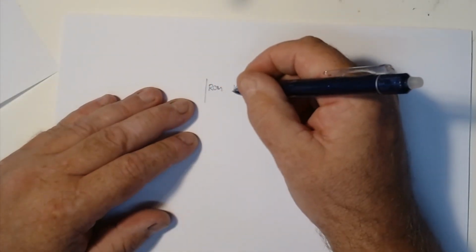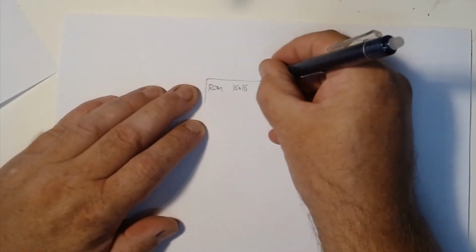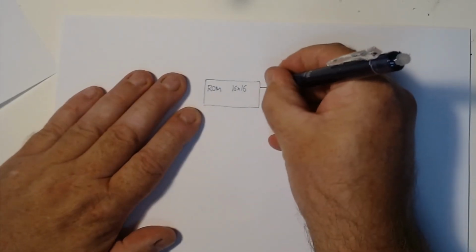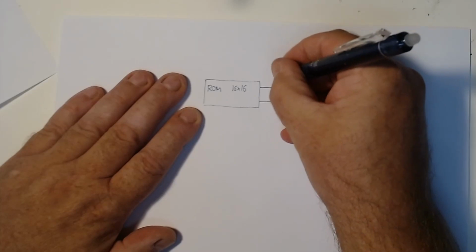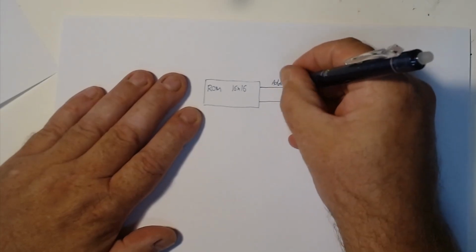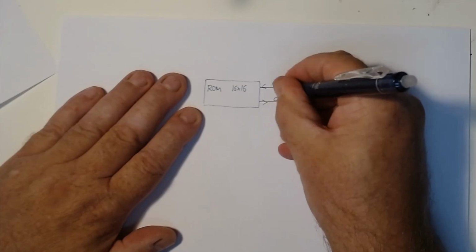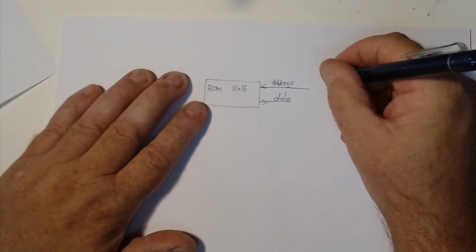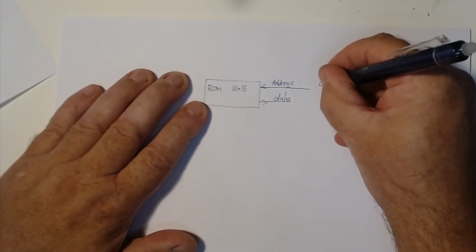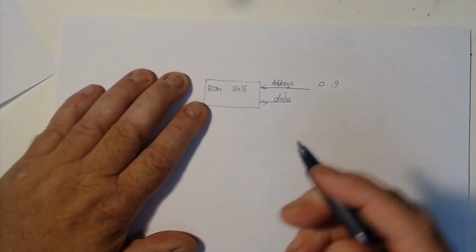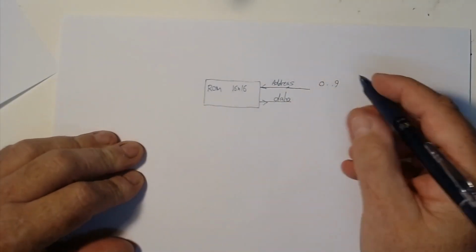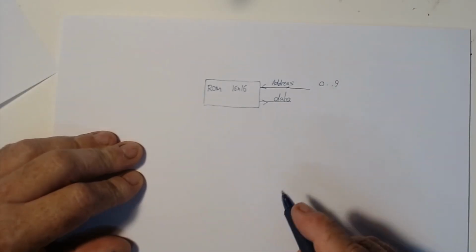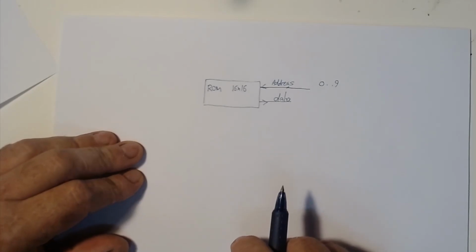Do we need to clock it out? Probably not. So our ROM can be as simple as that. There's no need for clocks or anything. So it's got two things. We've got an address in, and we have data out. So the address system, we haven't defined anything yet, but we've got 10 characters, so it could be as simple as 0 through to 9 as our addresses. And the data out will go to the input to the LED array that we've just been talking about.